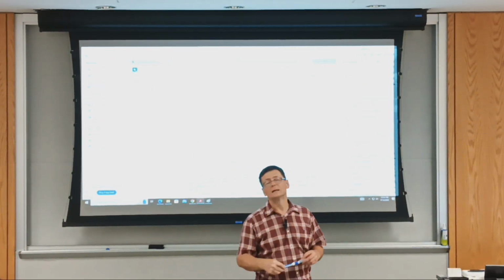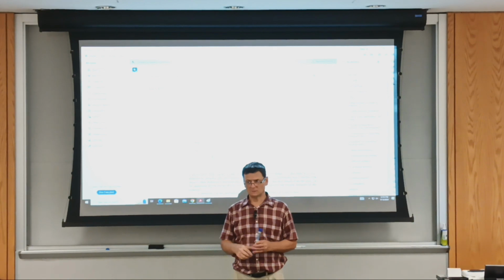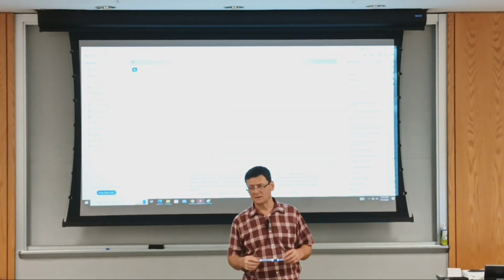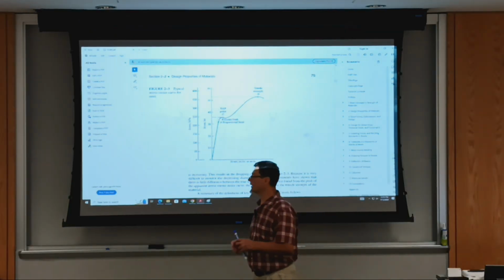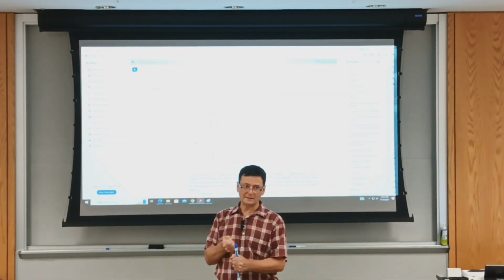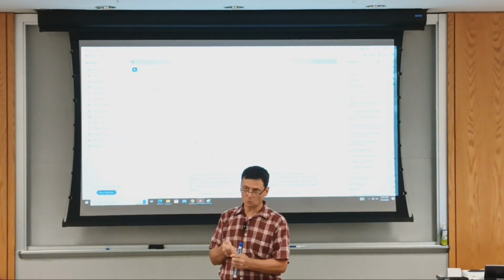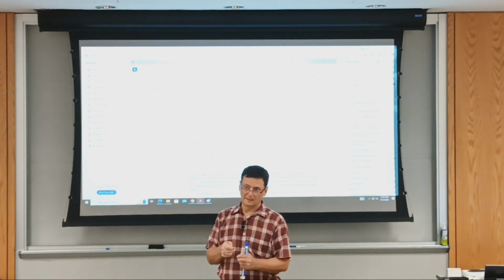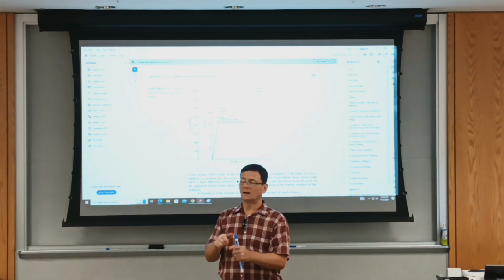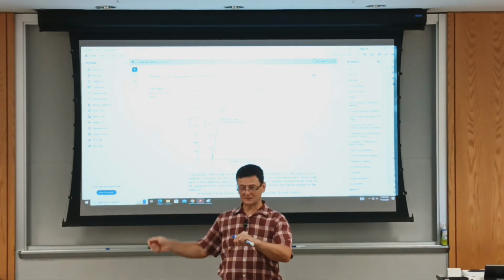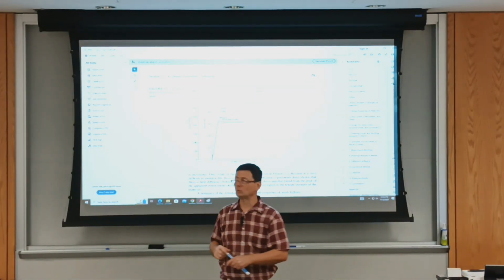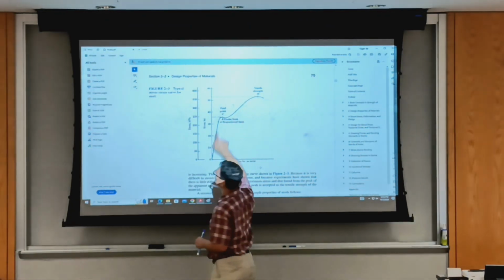This is how we get improved strength in cold drawn wire and thin bars. This is how, for example, if you take a pin and you heat it with a lighter at home, just make sure you don't burn your fingers, then you can bend it easily. You heat it with a candle lighter, red hot, and let it cool. And you can see you can very easily bend it where you reheated. What you did, you've undone the strain hardening.